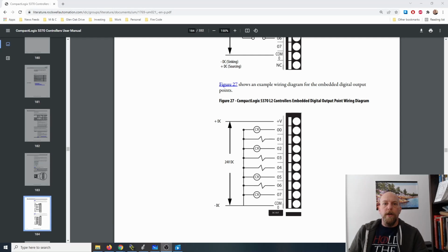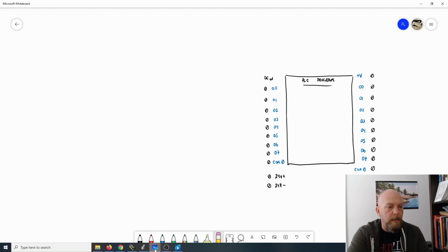All right, guys, so now that we've gone over the wiring, or expected wiring, on the inputs and the outputs, let's go back to that diagram and talk about the difference between XIC and XIO, because those are our main instructions that we're going to be making use of time and time again within our PLC programming. So we'll start off with the examine if closed. So a little bit of a lag as I draw this in and talk to you here. So we've got examine if closed.